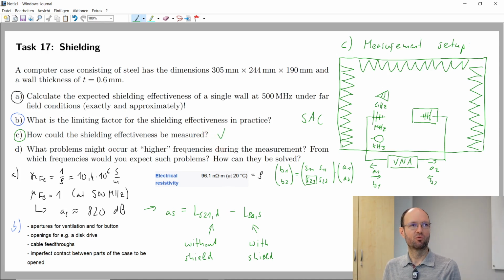Okay, so this would be one way to measure shielding efficiency. Take two antennas, measure the coupling between them with and without the shield, and take the ratio or the difference in dB, right? So this equation here is with gains rather than levels, but in decibel scale, let's say. Okay, so then we can come to the last question.